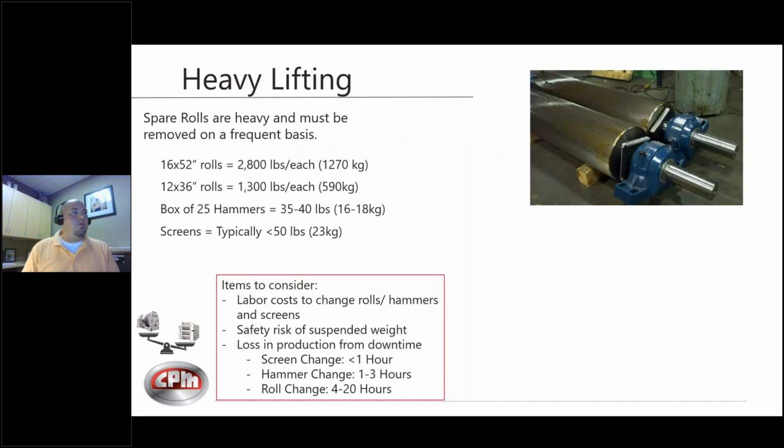Another thing to consider with roll crushers is the heavy lifting that's involved. You know, those rolls have to be recorrugated and reconditioned on a frequent basis. Certainly it will depend on the product you're grinding, how often you're running the machine. But I see there are some people that have to change out the rolls every few weeks. There are some people that measure that timeline in years. So again, it really depends on what you're looking at.